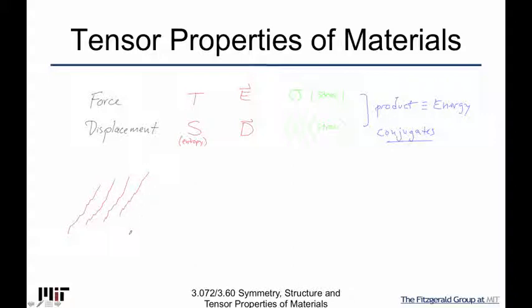I can have these polymer segments in a dense array where electrons can hop this direction, but then they conduct through excitons along this way. And if these polymers can be stretched through mechanical forces into particular orientations, you can imagine easily that if I were to put an electric field here, that the current may actually prefer, on average, to go this way.